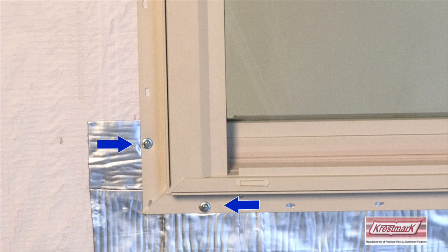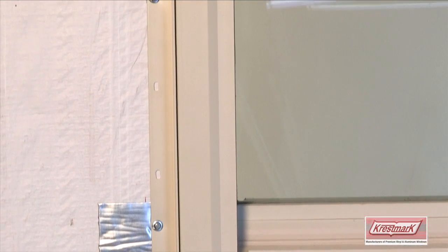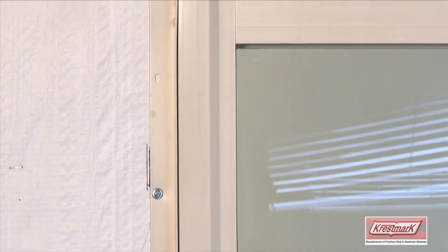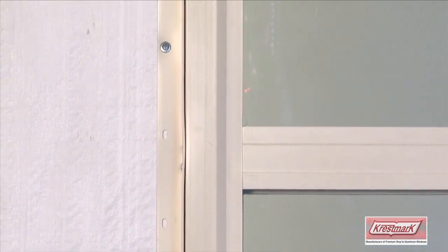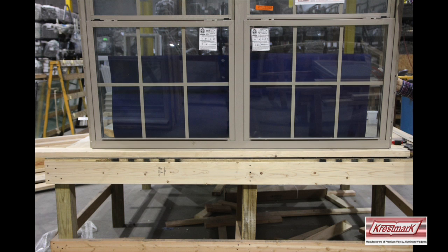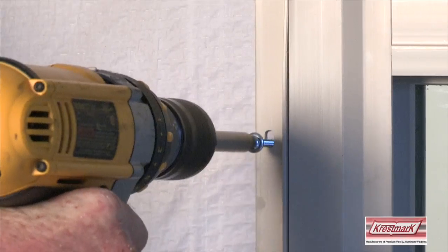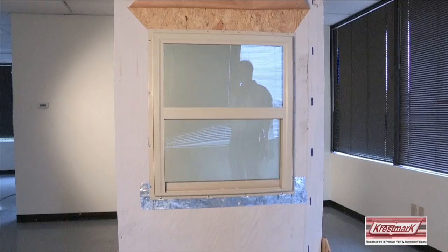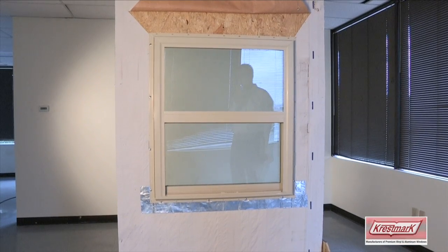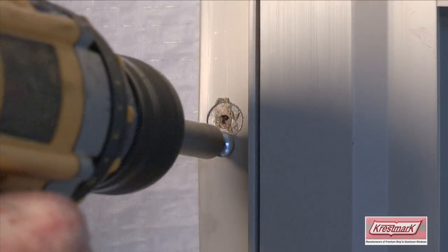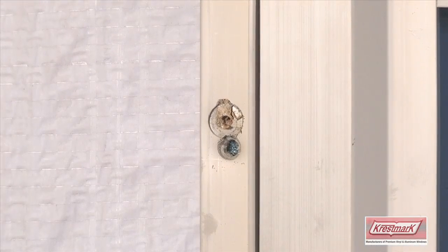Fasteners need to be spaced approximately 2 inches from each corner and approximately 12 inches on center around the perimeter of the window. The fasteners need to be long enough to penetrate a minimum of 1.5 inches into the wall framing. Combination or multiple window units must be fastened directly at the mull and approximately 6 inches on either side of the mullion. Fasteners should be centered in the slots, snug, but do not draw all the way in, similar to installing vinyl siding. This allows for normal expansion and contraction. If using pneumatic tools, adjust power not to distort or damage the nail fin.